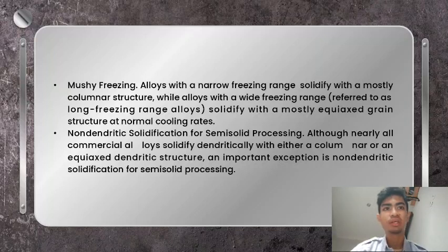Microporosity is particularly difficult to eliminate. The most effective method is to increase the thermal gradient, often accomplished by increasing the solidification rate, which decreases the length of the mushy zone. This technique may be limited by alloy and mold thermal properties and by casting geometry. In the casting of complex shapes or thin sections, alloys with compositions near the eutectic point are often preferable.